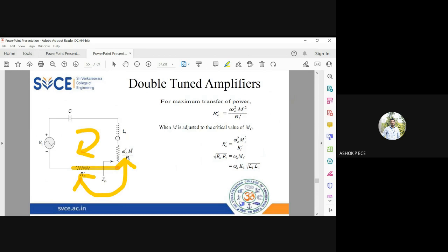Then the final simplified equivalent circuit, you will have VTH, RTH, RL. For maximum power transfer, you blindly apply the condition RTH equal to RL, right? Same thing here also. I have only two resistance values. For maximum power transfer to take place from this AC source, which is available at the input side, the value of resistance R naught dash and this must be the same.